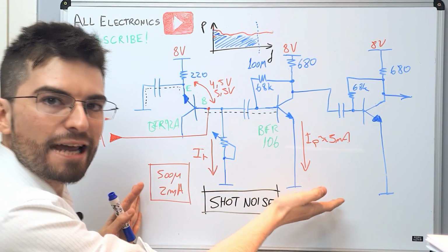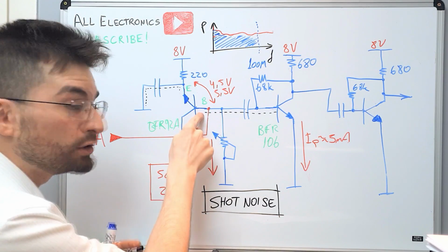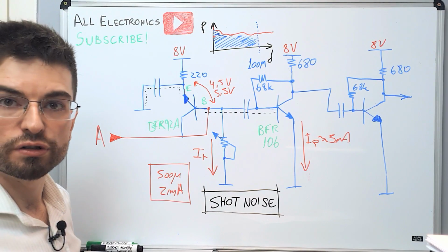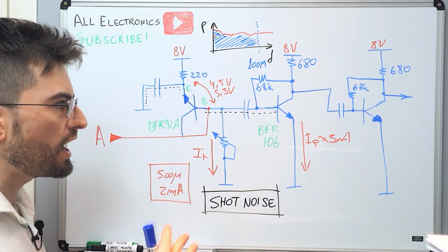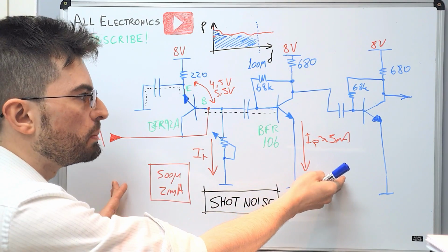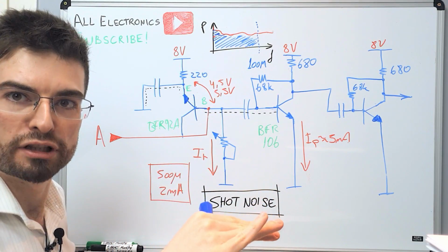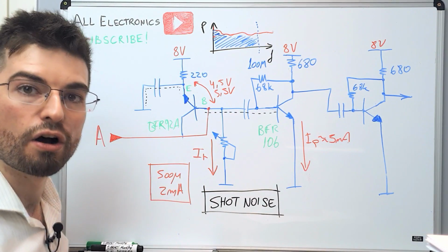So by measuring the gain of the amplification stage, we are able to approximate the noise generated by the transistor itself. And if you see on the article, you're going to see that it's very, very flat, much flatter than the full response, because what dominates the shape we are seeing on the spectrum analyzer is the shape of the gain function, the transfer function of the amplifier.